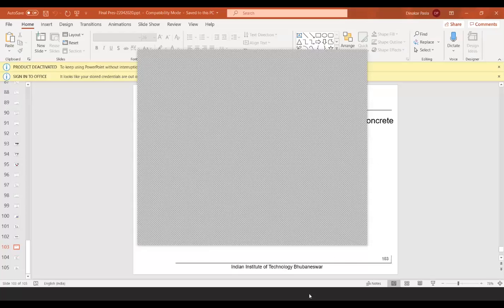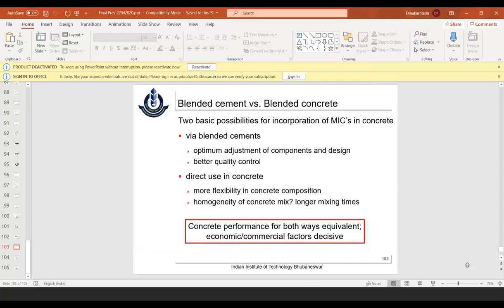Actually, I'll just tell my experience also, because most of the sites, in the name of sand, start using dust, which at times consumes more water in the concrete mix and leads to more shrinkage as well. So that is one of the practical issues.